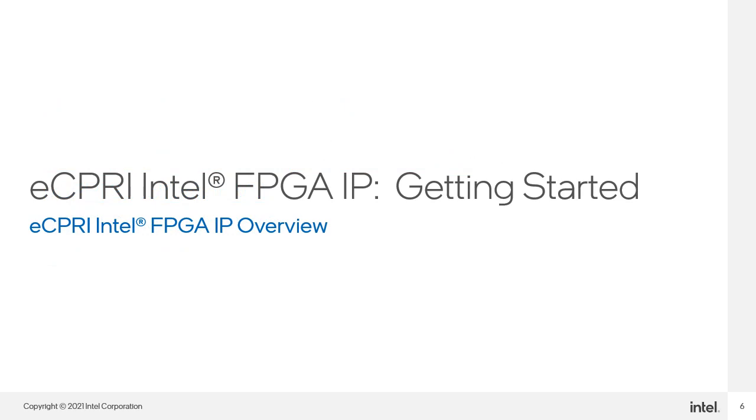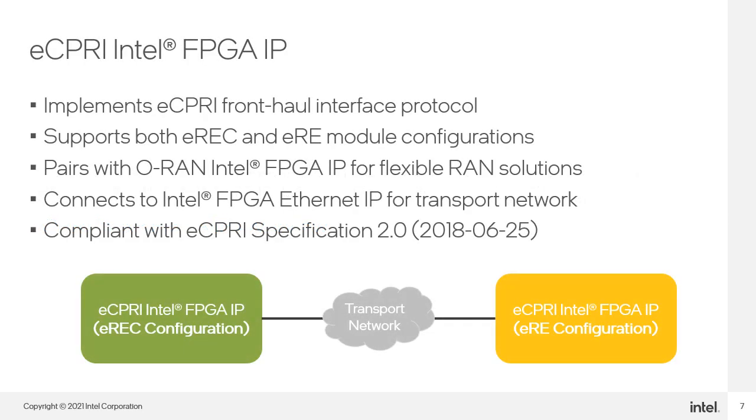So let's start with an overview of the eCPRI Intel FPGA IP. The eCPRI IP implements the eCPRI interface protocol used in fronthaul connections between the baseband unit and the remote radio head. Using the eCPRI packet-based methodology, additional bandwidth can be transported using fewer fibers in comparison to CPRI.